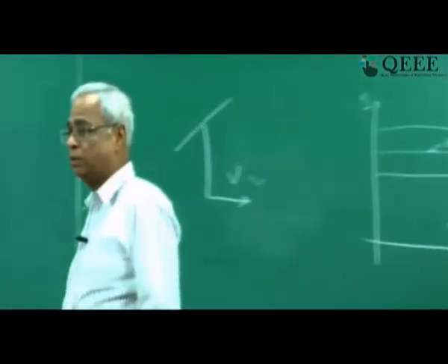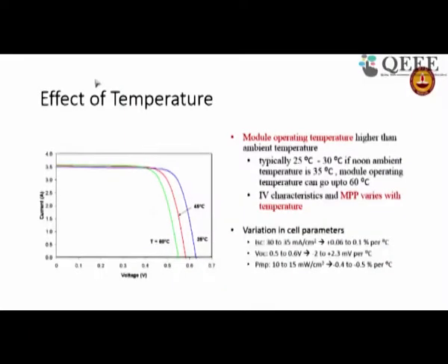Now, first one will ask, why 60 degrees? After all, temperature never goes up to 60 degrees. It may go up to 45, yes, if you take a city like Meerut or a city like Warangal in the summer months. Or in Andhra Pradesh there is a place which gets very hot, where they do stone cutting, Kadapa. But even then 46, 47, so why am I talking about 60? The first important point that we want to make is that we are talking about the panel temperature rather than the atmospheric temperature.